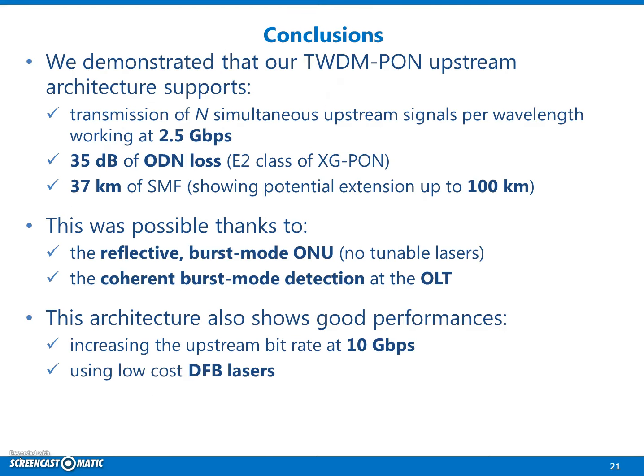To summarize, with this work I demonstrated that the proposed reflective burst mode passive optical network architecture fully satisfies the main requirements defined by the NG-PON2 standard for the upstream transmission, even without the expensive tunable laser at the customer side.